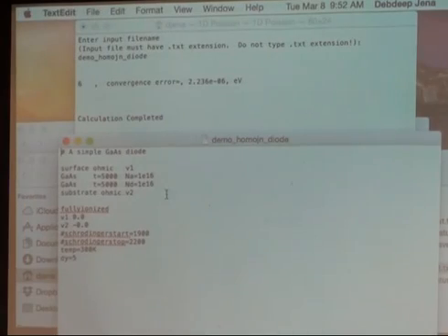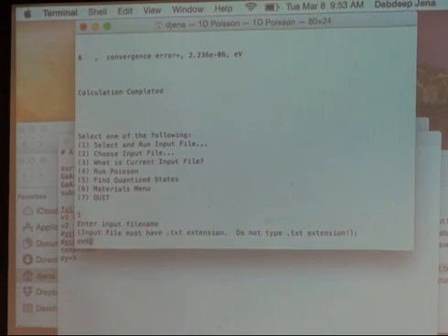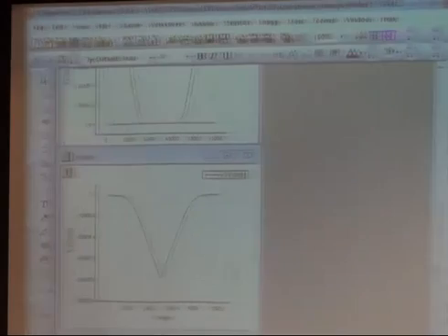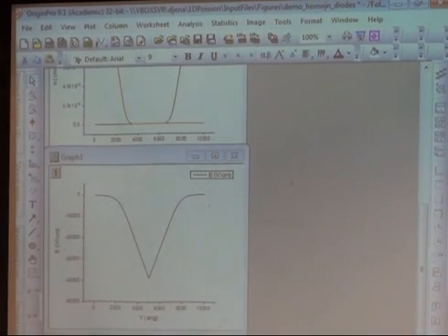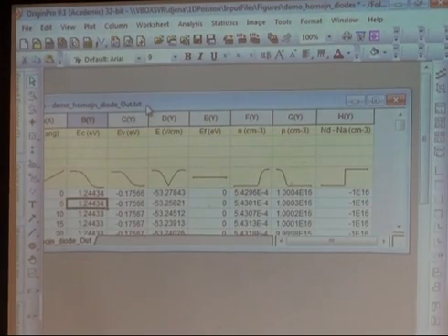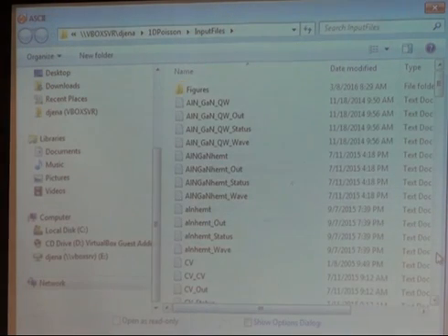So what you can obviously do is go in and say, I want a much heavier doping. Let's say I change it to 1E18 from 1E16. What do we expect to happen? The depletion region is going to shrink, the field at the junction will go up, the band will be much sharper, and all that. So let's look at that. Homojunction diode. All right, let's run. Oh, this is even better for whatever reason, I don't know. And then we import it.